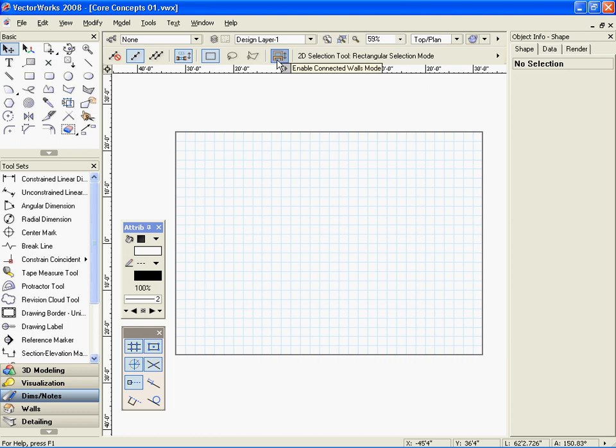Normal scale, found under the Zoom submenu and View menu, shows my drawing at a zoom ratio of 100%. In Vectorworks, we typically draw at the scale we use to print, as opposed to drawing at 1:1 as in some CAD programs. Therefore, 100% shows me the approximate size objects will display when printed, and is a good way to check that I've drawn the right amount of detail for the scale.